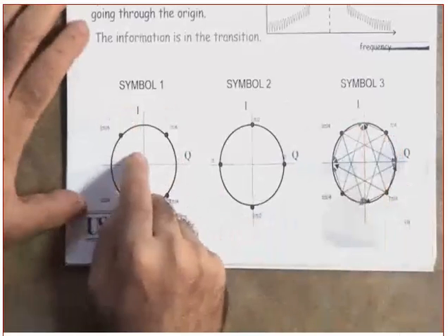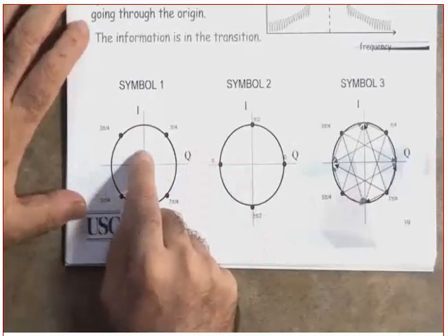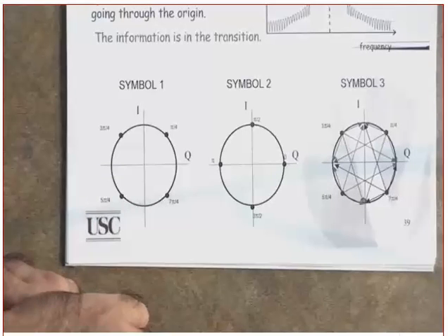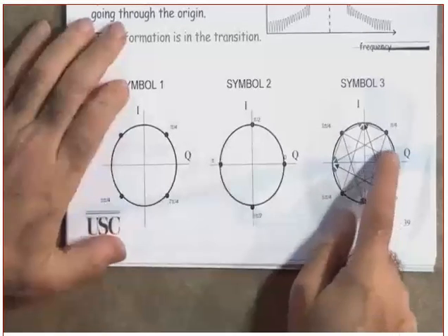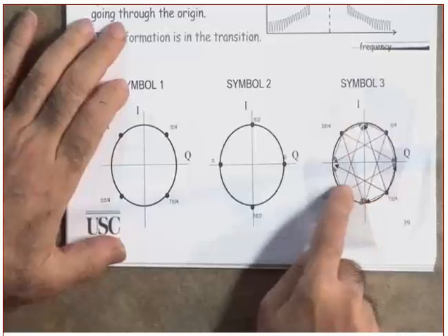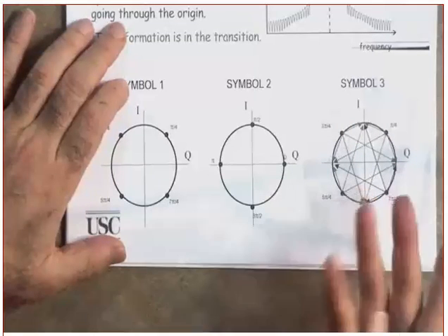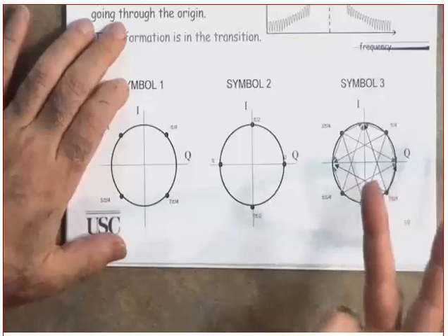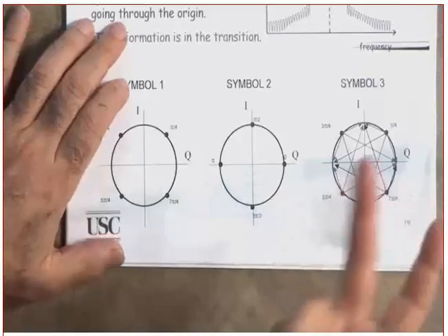Why? Because you are taking from here to here. You are not taking two signal points from here. Yes or no? So it's as if you have, how many signal points do we have? 8. But don't get fooled by 8. Each one is representing how many bits? How many bits each symbol?